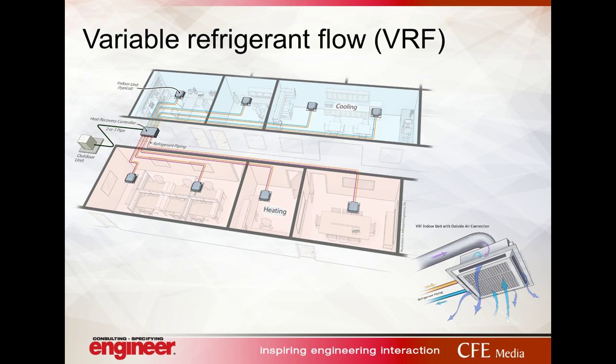Now, the issue with VRF systems is they require a lot more refrigerant, because now instead of running water, we're running refrigerant lines all throughout the building. This makes them, according to what ASHRAE Standard 15 describes, as a high-risk system. That means that now we have to look at complying with ASHRAE 15, which gives us a refrigerant concentration limit that is calculated based on if this entire system were to have a leak in the smallest occupied room and were to evacuate the whole system.